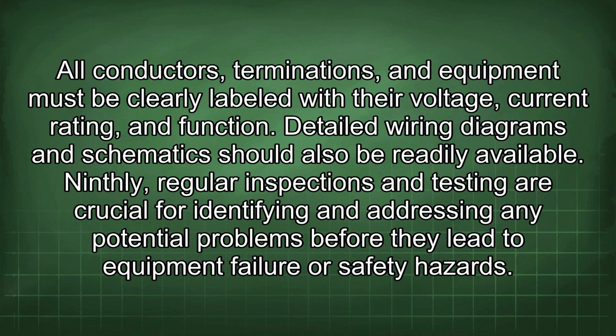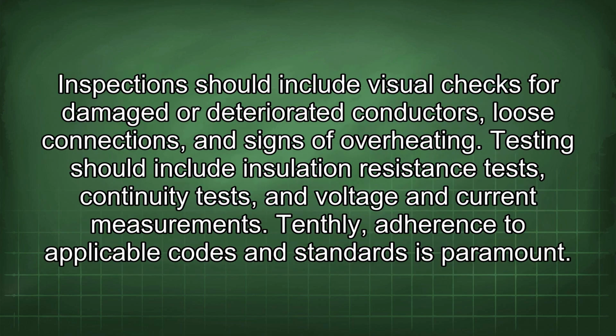Ninthly, regular inspections and testing are crucial for identifying and addressing any potential problems before they lead to equipment failure or safety hazards. Inspections should include visual checks for damaged or deteriorated conductors, loose connections, and signs of overheating. Testing should include insulation resistance tests, continuity tests, and voltage and current measurements.